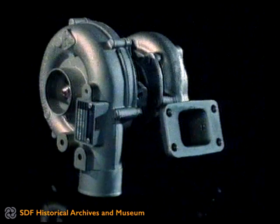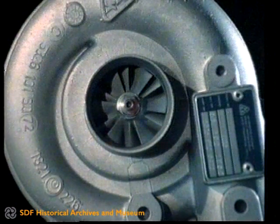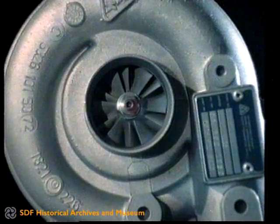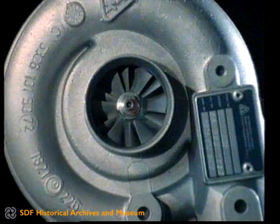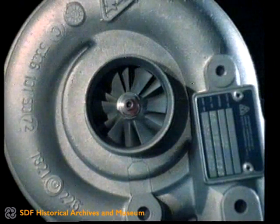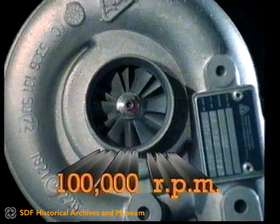Turbocharging with a turbo compressor leads to increases in power of up to 30%. The designer has to give the engine parts more ample dimensions and take into account that the greater power produced entails the removal of more heat. For this reason, the cooling system has to be enlarged and great care taken in the manufacture of the valves and piston rings, in the choice of the materials used for them, and in controlling the temperature of the lubricating oil, which must also lubricate the delicate moving parts at more than 100,000 RPM of the turbo compressor.